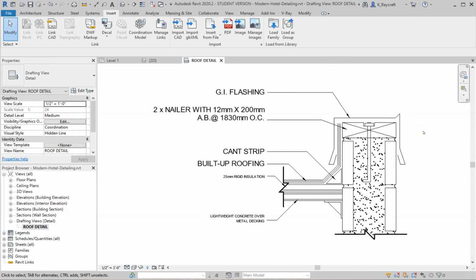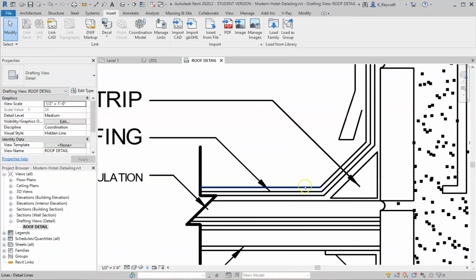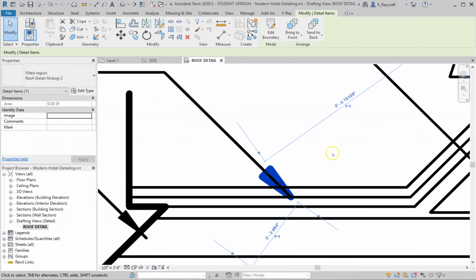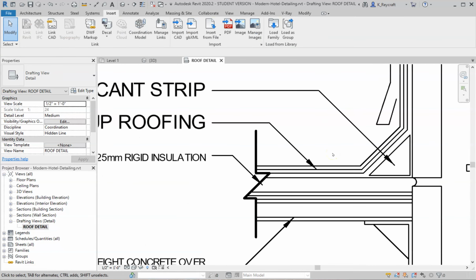Number one difference was that the text actually now matches what the default text style was, and usually the default text style is the style that you've been using all along for notes. You'll see that the hatching pattern is still a hatching pattern, which is great, but you'll see that lines, individual lines, are just that, they're individual lines. The arrows or the leaders are actually separate lines, and the arrowheads are separate objects. That's an issue. We're going to have to fix that.